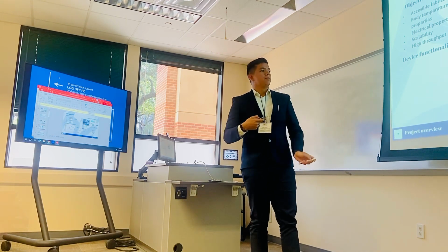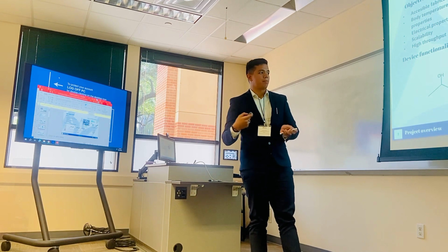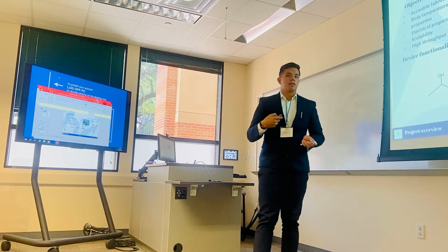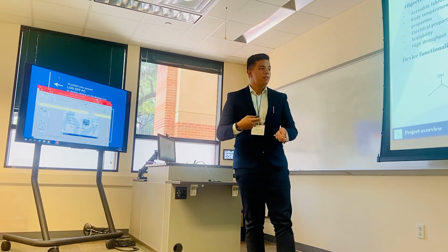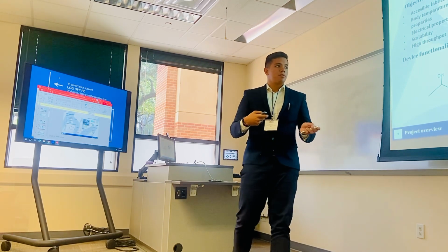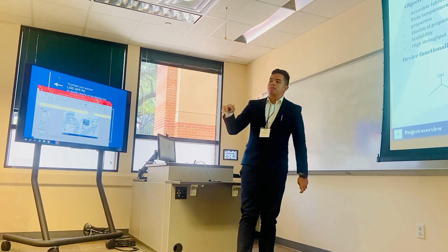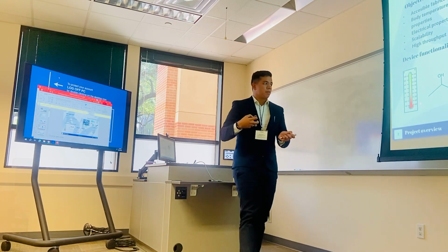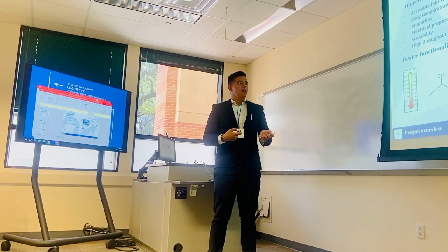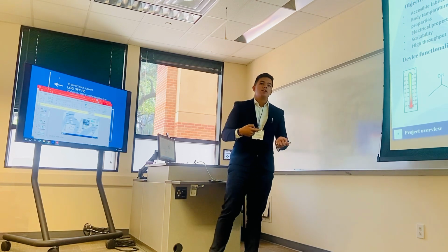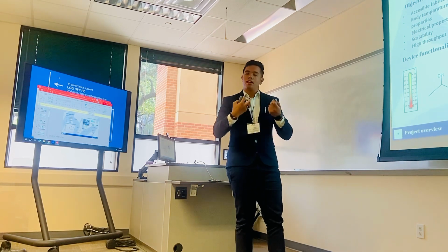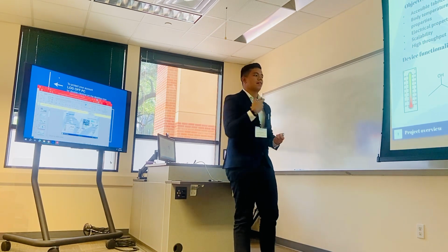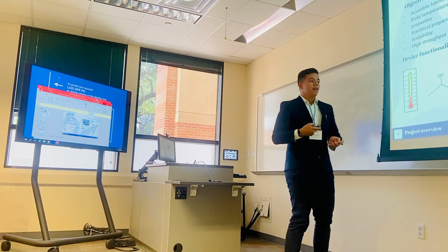In a literature review, we saw that polyvinyl alcohol, which is also a thermoplastic, was used to sense strain properties and body temperature properties. Not exactly with woven textiles; it was used in non-woven and other types of polymer substrates. But when this kind of thermoplastic is exposed to a heat source, its individual monomers stretch, which deforms the material, but in a way that we wanted to functionalize so that we could sense it as some sort of change in resistance.